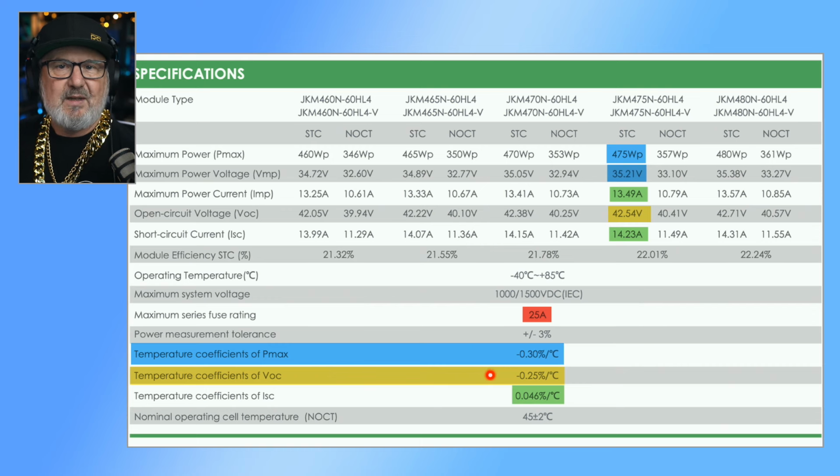And like I said, you can be lazy and just use table 4.1 out of the standard, but it's not in your interest because the default temperature coefficient in 4.1 is minus 0.45% per degree Celsius. Panels these days are approximately half that now. That means there's half as much voltage change with temperature as there used to be, and therefore, particularly under colder conditions, you get much less voltage rise. And that can mean you can put more panels on, so that's pretty cool.